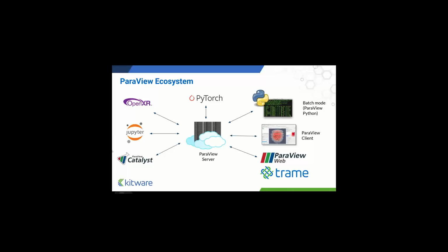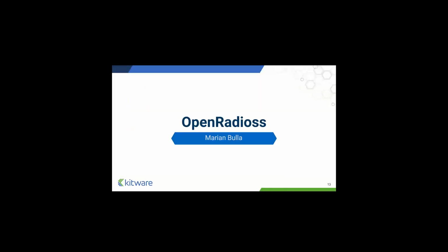One other bridge I'd like to mention is Catalyst, which is a way to do in situ analysis: instead of opening a file from disk, you connect to your numerical simulation while it's running, and you can post-process the data live from the simulation memory. It's very powerful. This slide illustrates that ParaView is not just a viewer, it's a whole scalable ecosystem. As soon as you can open your data in this ecosystem, you have lots of possibilities. So that's it for the short ParaView introduction.